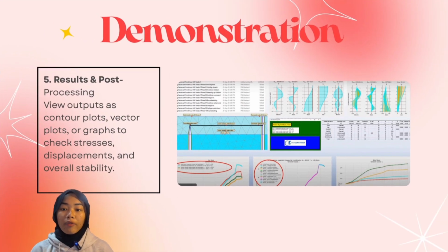Last but not least, we have post-processing and results. Once the calculations are done, the software provides a wide range of output options. You can view results from contour plots, which show areas of high stress or displacement. Then we have vector plots showing the direction of movement, and graphs. This allows you to check the stability of your design and identify potential failure points. I think that's all from me. I will pass to Sarah.